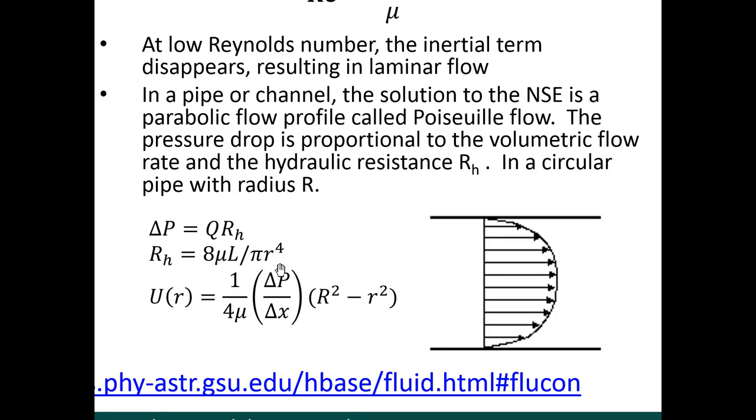So what this means is that the hydraulic resistance of a microfluidic channel goes up very dramatically at the microscale, to the point where you actually need large amounts of pressure to drive fluid through there. This could be considered one of the disadvantages of microfluidic systems: you do need large amounts of pressure to drive fluid through a channel.